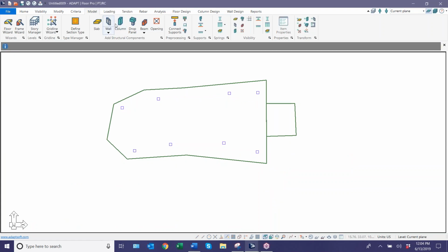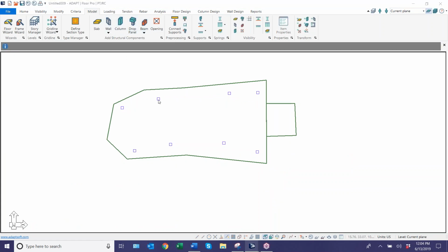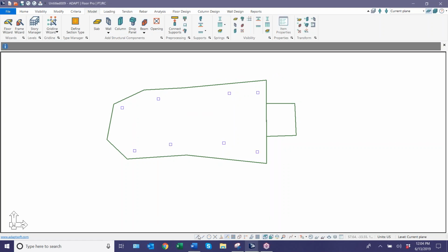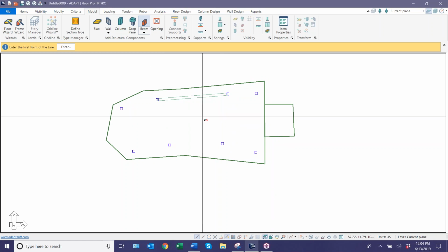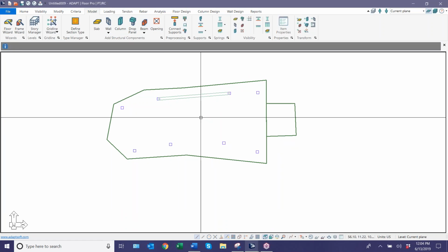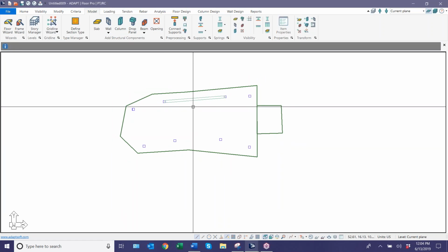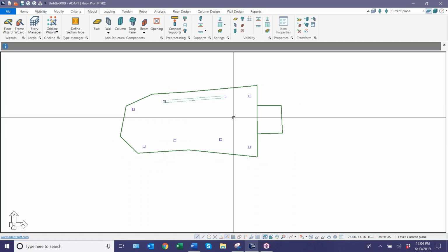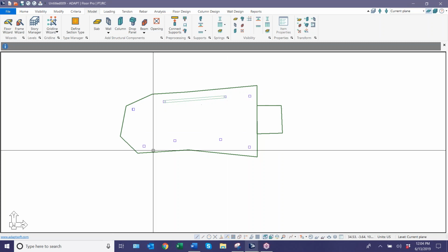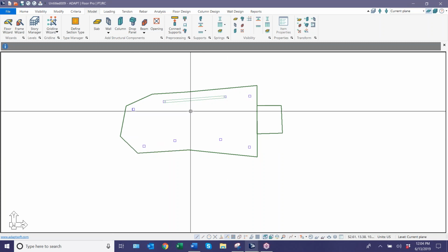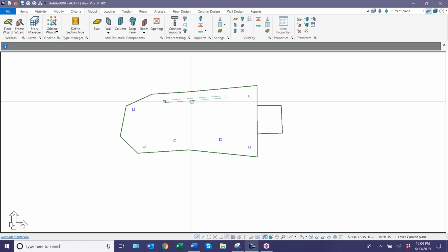And I'm also going to add a beam. So we'll go here and add a beam. Now, in some cases there's a mysterious notion that Adapt Builder doesn't design beams. And in fact, it does design beams. It's just a matter of how the beam is being processed, and it's really contingent on the setup of the support line. So let's assume we want to design these two strips. This is a two-way slab with an integrated beam in this case.